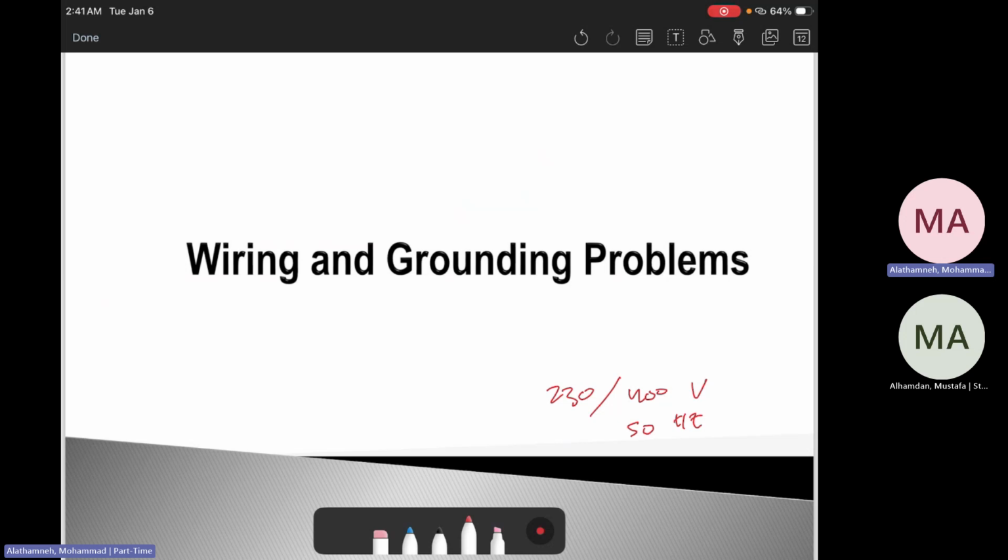So our goal today is this: when someone tells you I have noise in the output voltage, or I have noise in my home, or in the electronics sector, you need to know that these problems can come from the grounding. Especially when somebody says I get a shock from the power cabinet, or my circuit breaker trips randomly for no reason, or the PLC misbehaves, the things you need to ask yourself are: is there a ground, or is the grounding missing? Is there a neutral to ground connection?